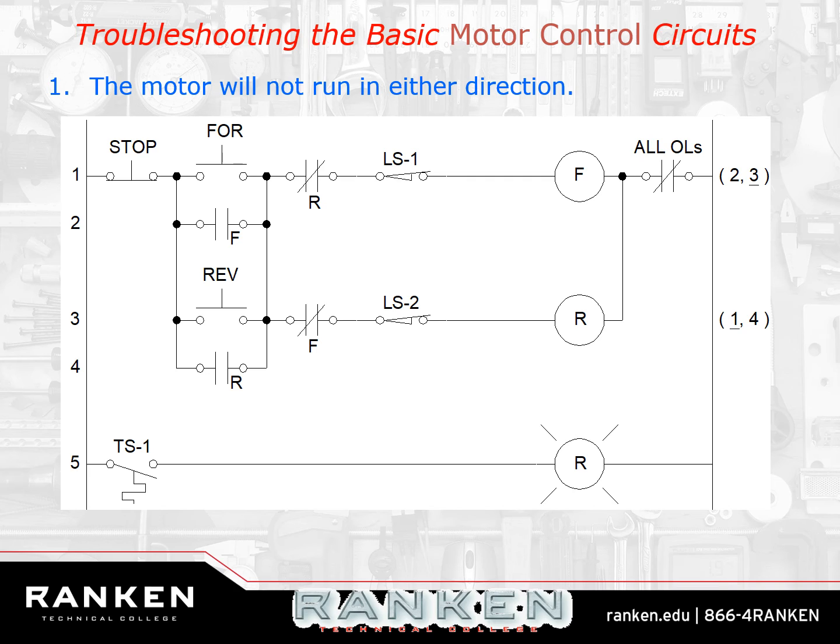If it's not the overload and it's not the stop button, then yeah, we're going to have to dig deeper. But chances are, it's that guy. That's where I would start. Because that's another one of those cool things, right? You walk out, the thing won't run, you push the reset on the overloads, it goes click, and it starts running again. Now you look like a wizard again, because you just expecto patronum, right? Pow! Drop the mic and walk away.